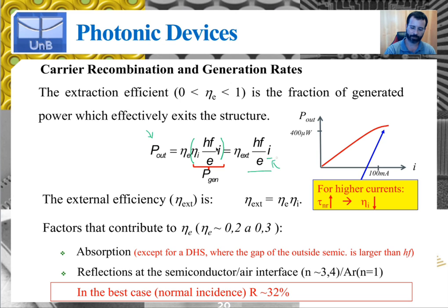We see here again that the power coming out of the device has a linear relationship with the forward current I, up to some point. If you raise the polarization voltage too much, the device will begin to heat, and then the total non-radiative recombination lifetime will decrease, and the internal quantum efficiency will begin to decrease as well.